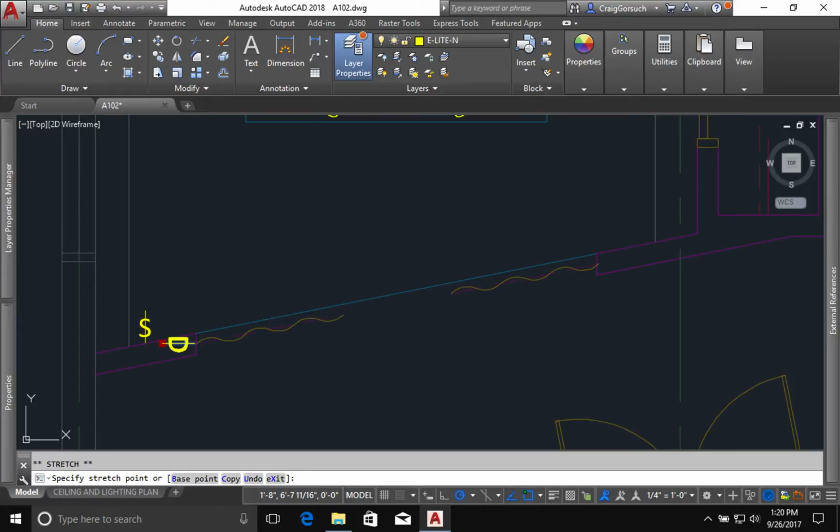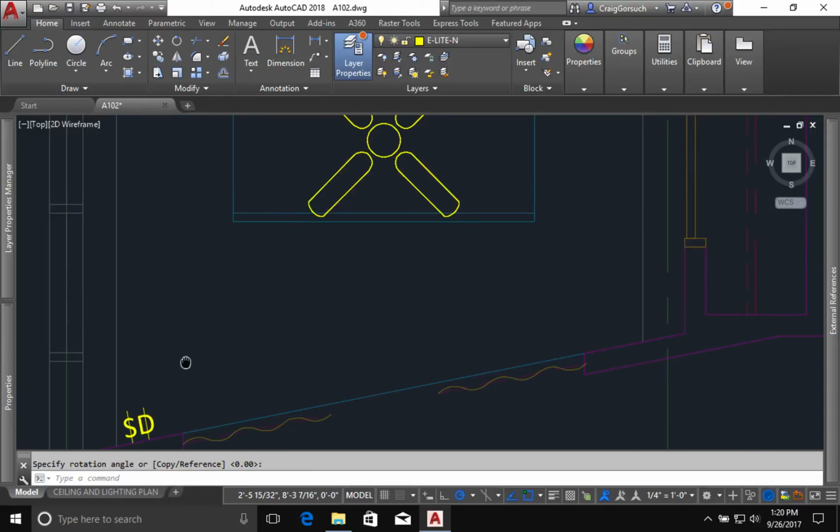And you'll notice there's the dimmer switch and then there's a regular switch, and they're regular letters. They follow the same rules as text if you need to rotate them. So you'll either read them from the bottom edge of the sheet or from the right-hand edge of the sheet. In this case, even though I have them on an angle, they're still readable from the bottom edge of the sheet, so that part's fine.